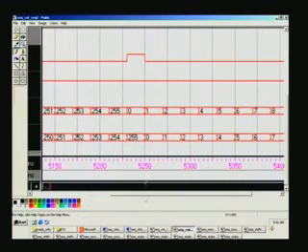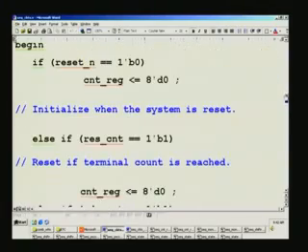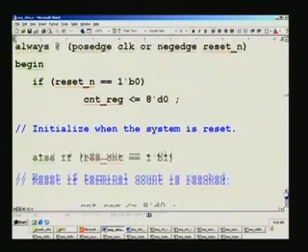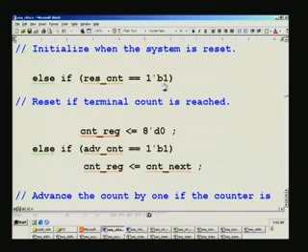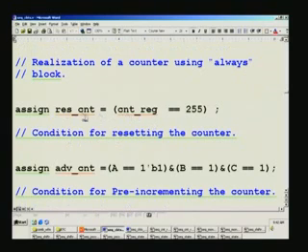So you can see this signal here, which resets the counter. This is the same as this 255, same duration, because it is a combination circuit. When reset count has become 1, that is, reset count is 1 if counter edge is equal to 255, then only this action takes place, and this is a combinational circuit as we have seen. So the moment 255 is encountered, immediately it will go without delay. Of course, there will be a gate delay, which we can see only after back annotation.